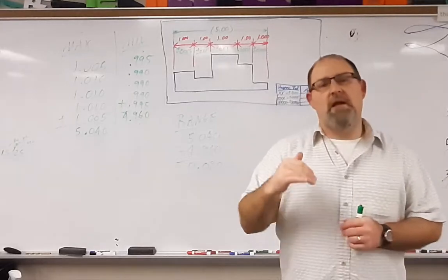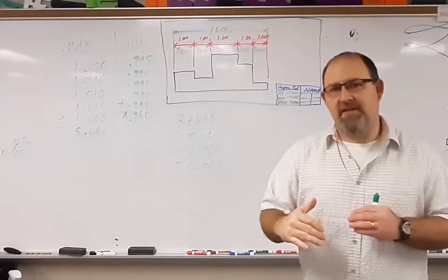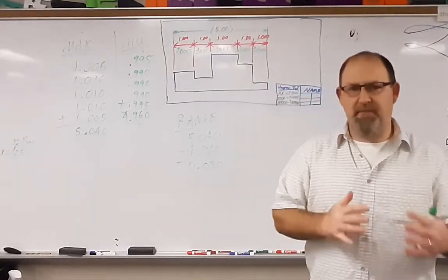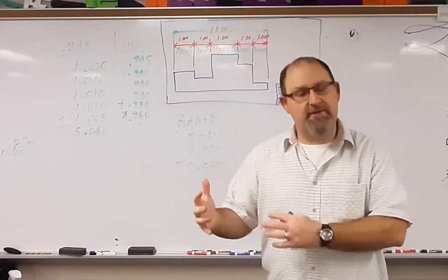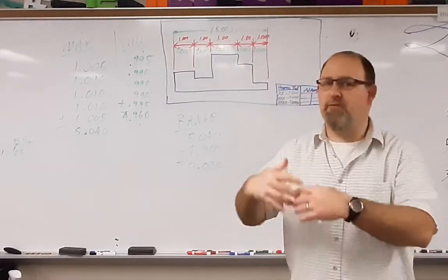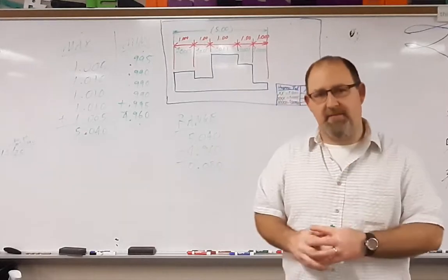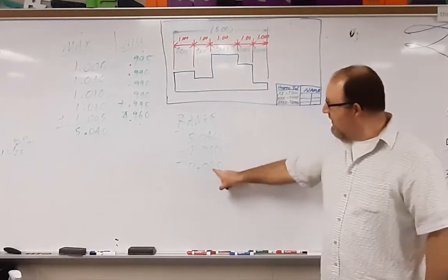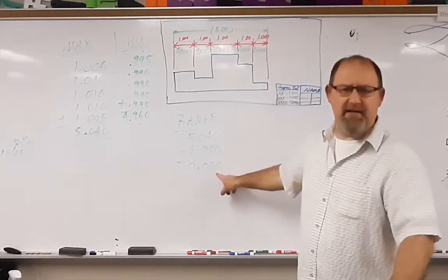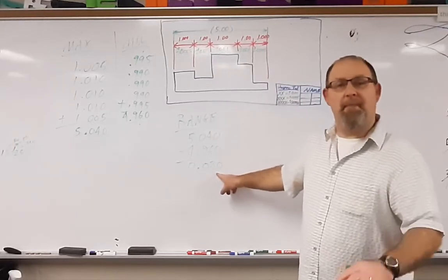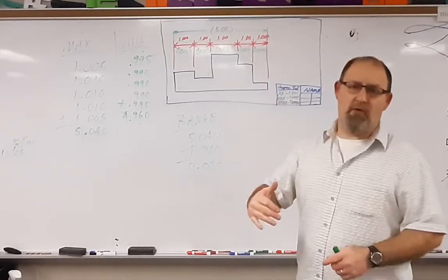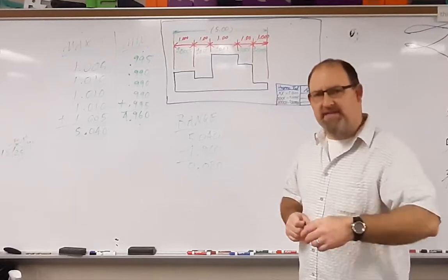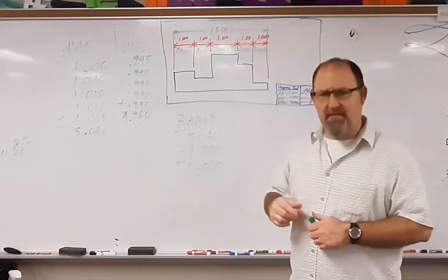Remember the rule, you want to design things that have the loosest tolerances possible where it's still fully functional and safe and won't break after 3 uses, you know, that type of thing. The reason for that is we can always make tolerances tighter, but the tighter the tolerances, the more your cost goes up. So as engineers, as designers, you need to keep that in the back of your mind.